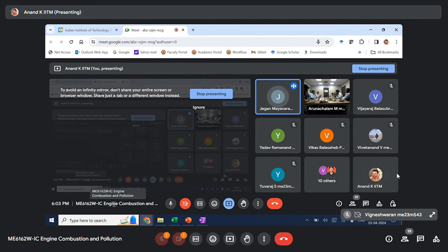But sir, in two-stroke marine diesel engines, we have two encoders, one for safety redundancy. The first encoder we always take at exact 0 degree TDC of the crank angle, which is the first unit at TDC. The second encoder we take with an offset of 45 degrees. Basically, that is to have a difference in the references, so that even if one encoder fails or has a problem, it should not replicate the same, because the control systems are of the same circuits. So it should not have a mismatch.